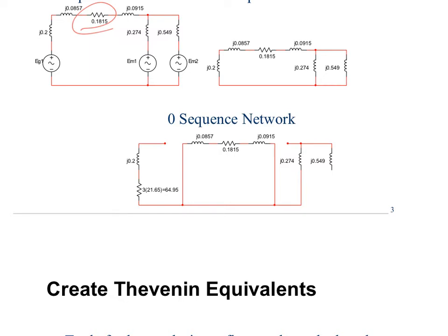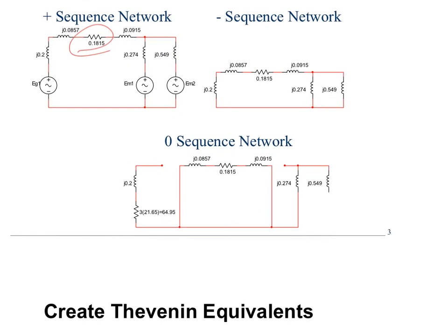Remember how we talked about coordinating systems? Isn't the generator system here electrically isolated from the zero sequence perspective from the transmission system, which is electrically isolated from the next generator system? So in terms of coordination, I don't have to worry about coordinating those systems because the current doesn't actually transfer through.